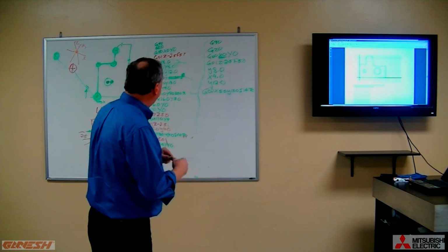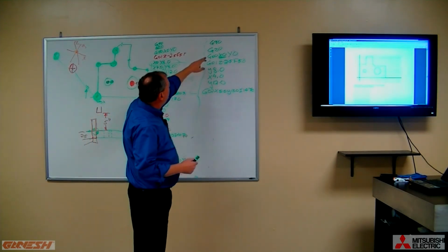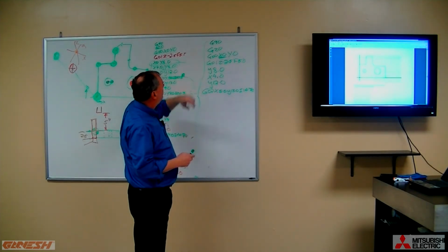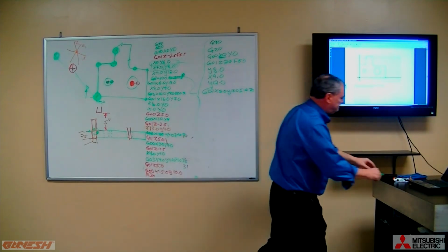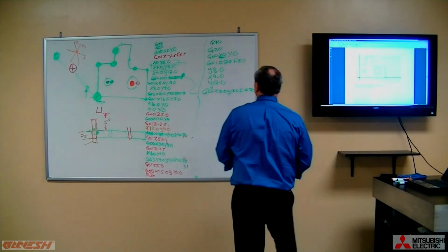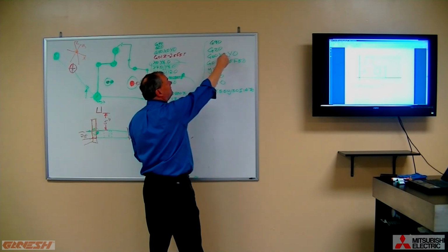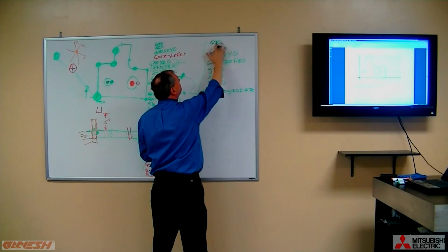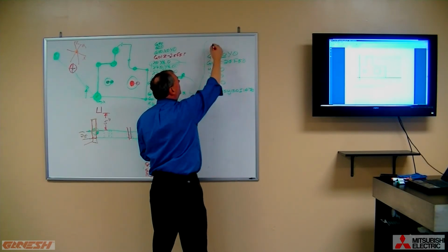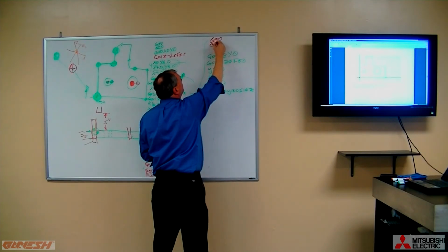And now I'm going to introduce you to the spindle on code, which you're going to want to do before you start putting the cutter into material. So at this point in the program, just above our positioning move to X0 and Y0, we will insert a command. So here we have our G90, we have our G20.